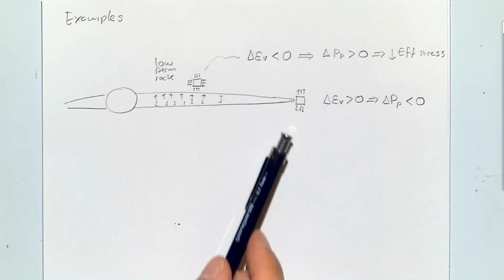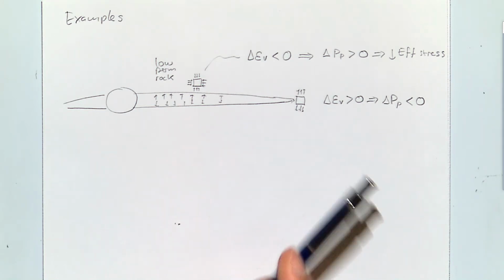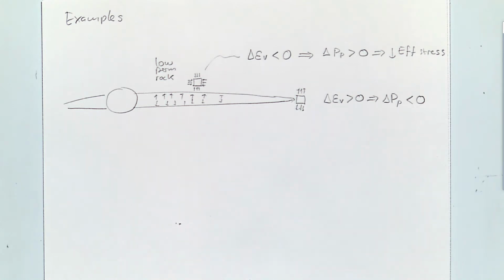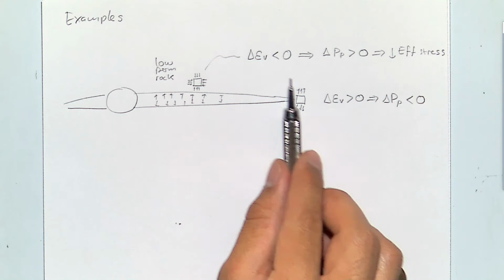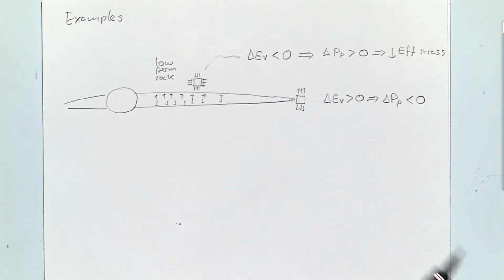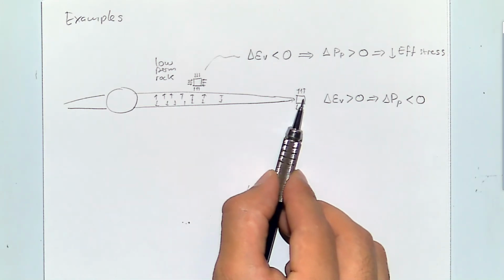Some people have done simulations about hydraulic fracturing, and they predict negative pressures at the fracture tip. That's something that doesn't really make a lot of sense. But I think the problem is that they start with pressure equal to 0 in the porous medium as a simplification, and a positive pressure inside the fracture, then they get negative pressure here.